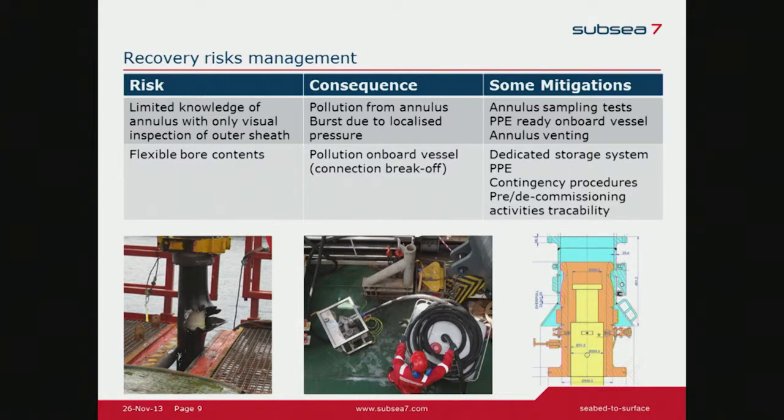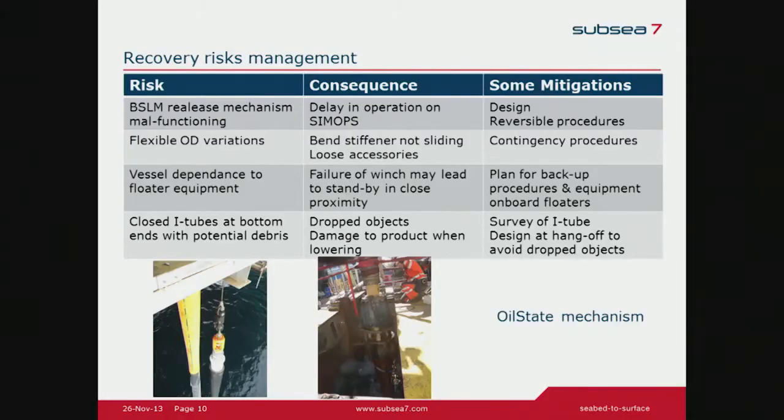Also, we can have a risk of the bend stiffener latching mechanism not functioning as we wish, which can delay the operations very much. This usually happens with our vessel in close proximity to the floater, and I will come back to that later.